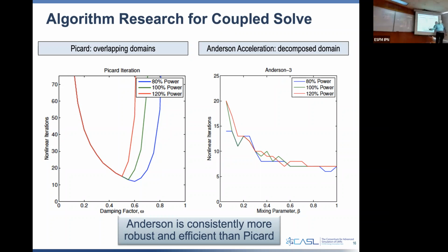We know we have a very small window of where an acceptable damping factor is. But when we put this in the elimination approach, we are intertwining these solves, where every single impact iteration we're completely solving for the temperature. So we're eliminating that temperature from the iteration.